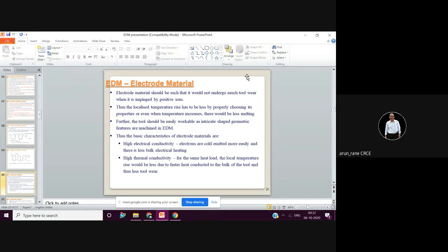So we engineers play around. If you want to do some cavity machining, EDM machining, then first in the soft condition, you do it on the CNC milling machine. You leave 1 millimeter stock all around, mill it out, which is very fast in the soft, virgin condition of the workpiece.